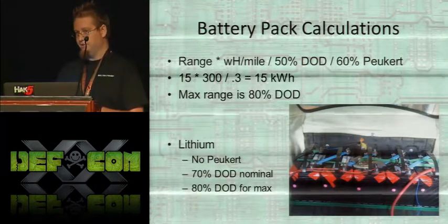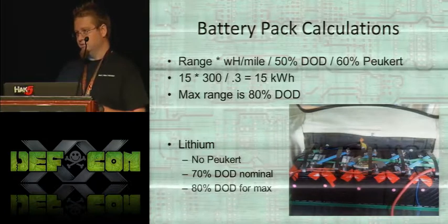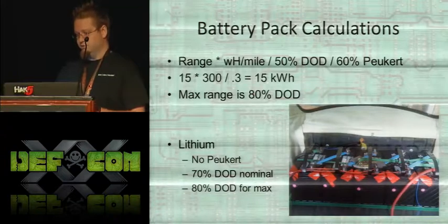For lithium batteries, you don't have that Peukert effect, so you can use a lot more of the batteries. Also, you can discharge them down to 70 or 80% without hurting the batteries, so you can get a lot more out of them.